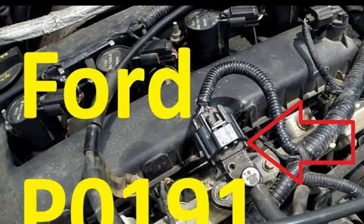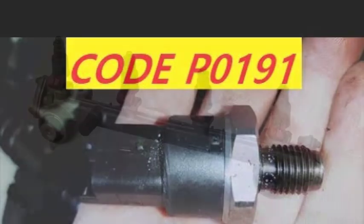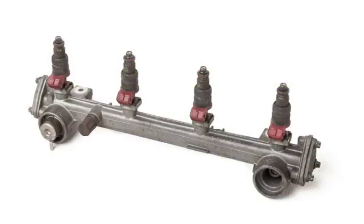There are several possible causes of the P0191 fault code. These include a faulty distribution manifold pressure sensor. The sensor itself may be faulty and need to be replaced. Clogged fuel filter. A clogged fuel filter can restrict fuel flow and cause the fuel pressure to drop. Fuel pump problems. A weak or failing fuel pump can also cause the fuel pressure to drop. Fuel injector problems. Leaky or clogged fuel injectors can also cause the fuel pressure to drop. Electrical problems. Wiring problems or a faulty ECU can also cause the P0191 code to be stored.